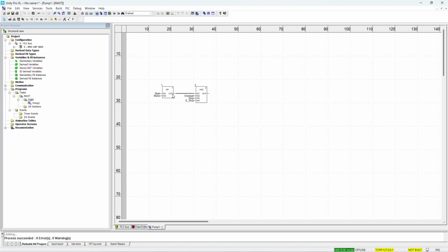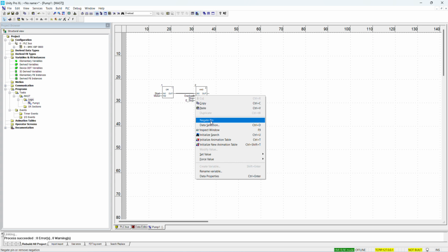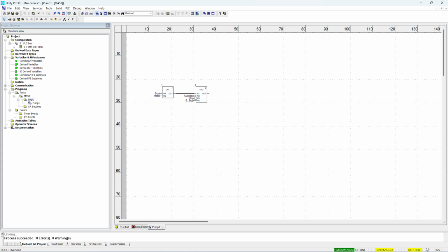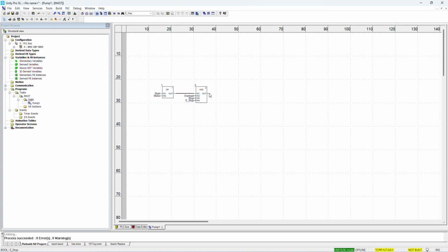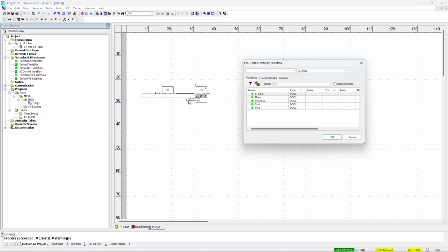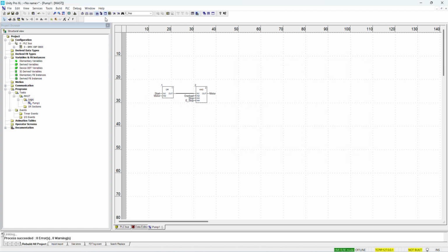But now this I said not, and remember for not we must have a not. Then I'm gonna right click there and negate this pin. And I say negate, there's a O there, that means not. Then right click there on that one again, put the not, right click there, not, and then I'm gonna have the motor, which is our coil.